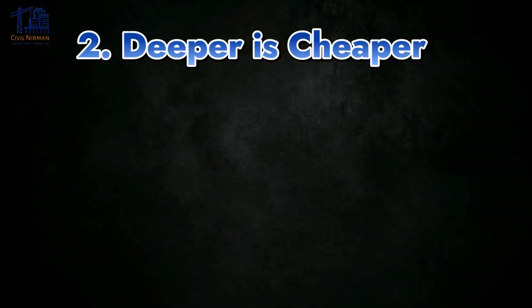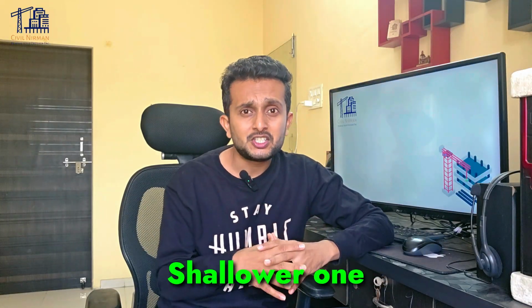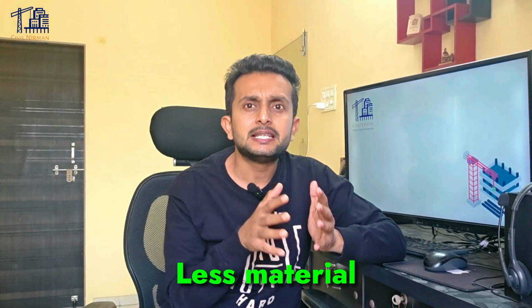Rule number 2. Deeper is cheaper. See, here is a surprising fact. A beam that's deeper and wider is often cheaper than a shallower one. You might think that it would be the other way around, but actually, a deeper beam needs less material to be just as strong because a deeper beam has a higher moment of inertia, meaning it can carry more load with less material, reducing the overall cost.